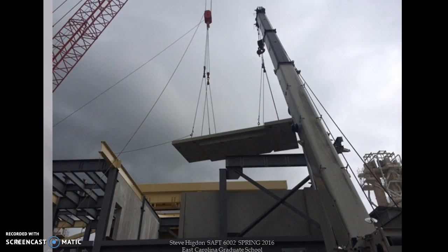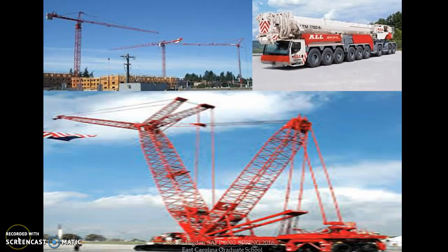The capacity of each crane and each component of the lift must be calculated. There are also inherent dangers in signaling a 2-crane lift. You will then need to choose a crane for the specific type of application that you're going to be using. You have to know a little bit about load charts to understand what the crane is capable of. This is called the capacity of the crane, and it's very important in planning a critical lift.